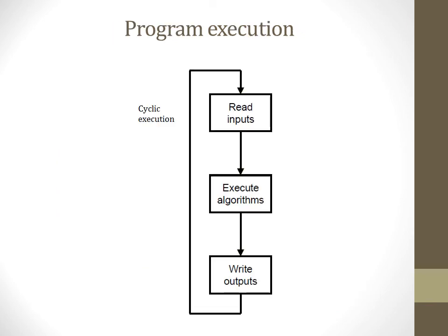In this part of our lecture we need to know in detail about program execution in the PLC. It's cyclic execution. First of all, the PLC reads inputs, which contain information from the plant or control object.